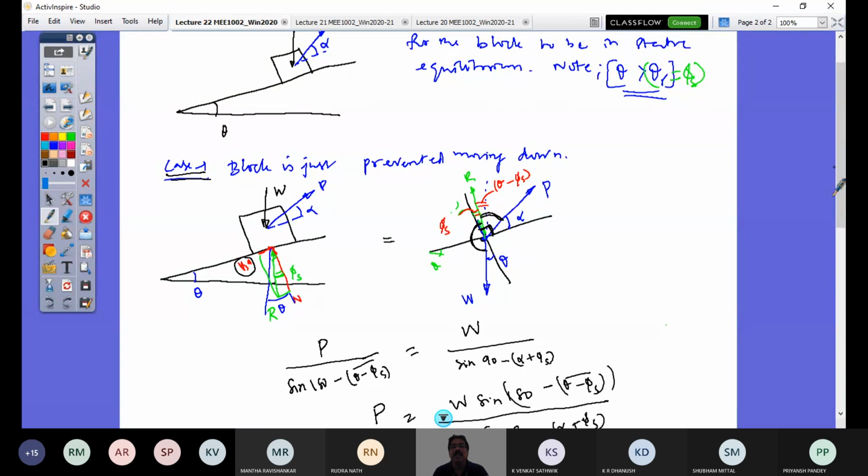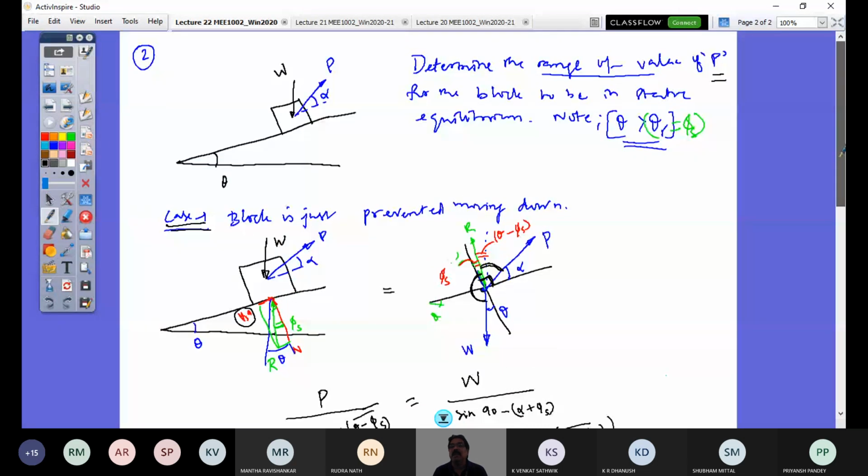That becomes easier if the trigonometric terms come like this. Maybe I have taken more time to explain, but this is a faster way than considering individual components by conditions of equilibrium. Both are complementing methods, but I would insist that you solve wedge friction problems by Lami's theorem whenever 3 forces act on the block.